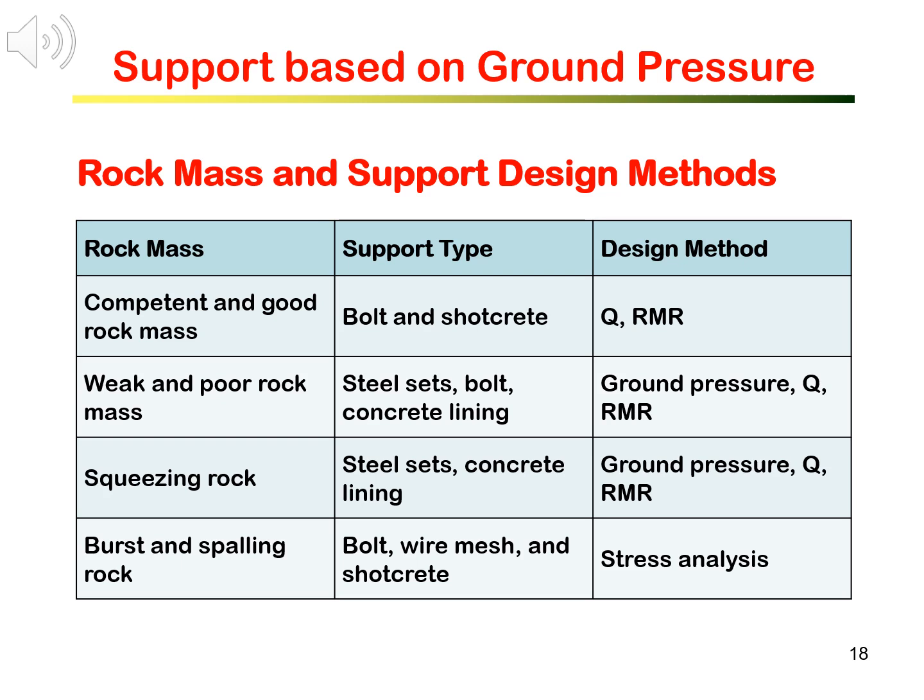For weak and poor rocks, swelling and squeezing grounds, while rock mass classification systems can be used for support design, ground pressure analysis provides a good estimation of load and deformation to be carried by the support, and hence design accordingly. Rocks facing stress problems should always be subjected to stress analysis to design the appropriate support.